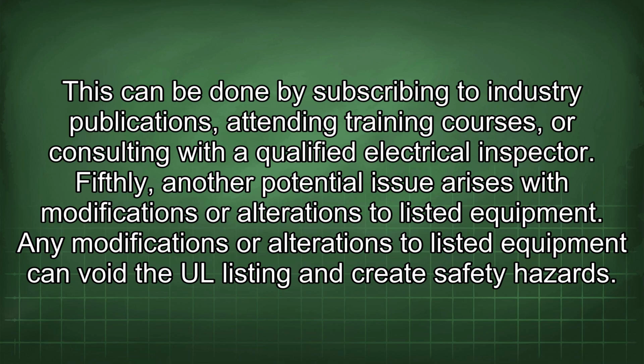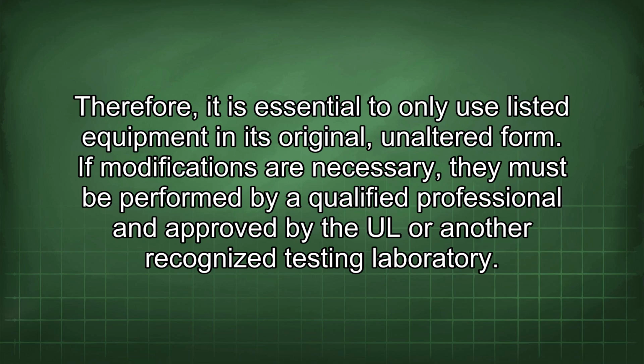Fifthly, another potential issue arises with modifications or alterations to listed equipment. Any modifications or alterations to listed equipment can void the UL listing and create safety hazards. Therefore, it is essential to only use listed equipment in its original, unaltered form. If modifications are necessary, they must be performed by a qualified professional and approved by the UL or another recognized